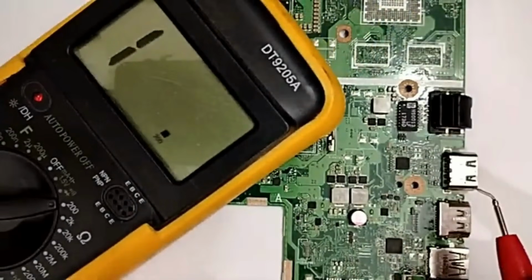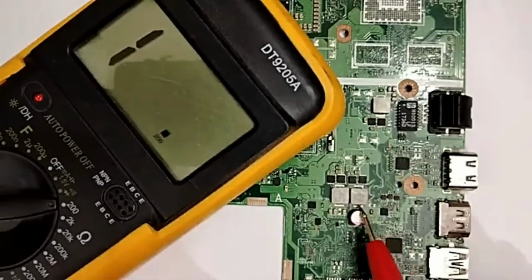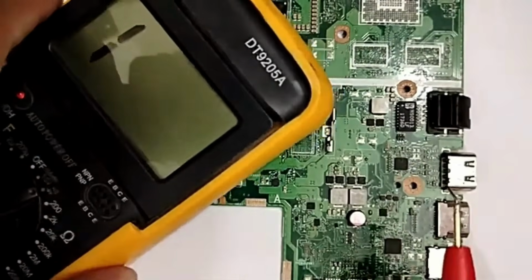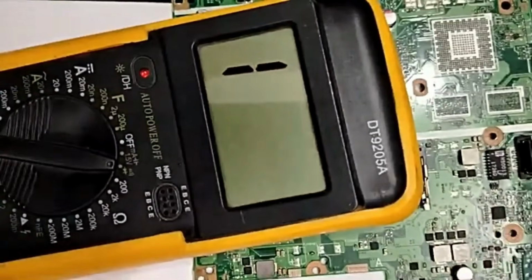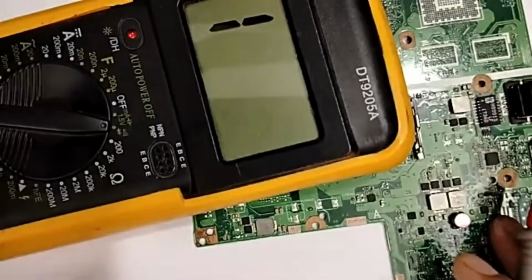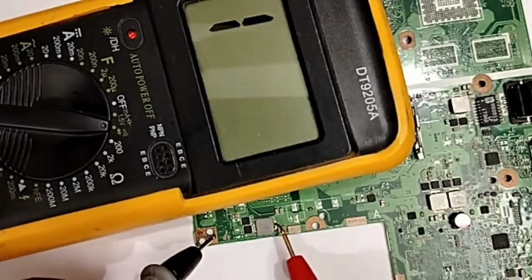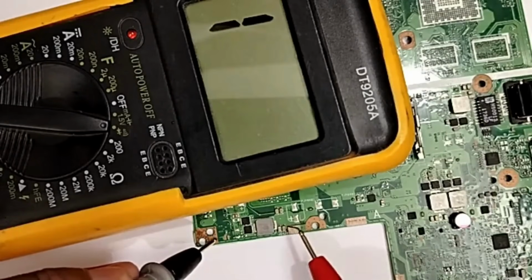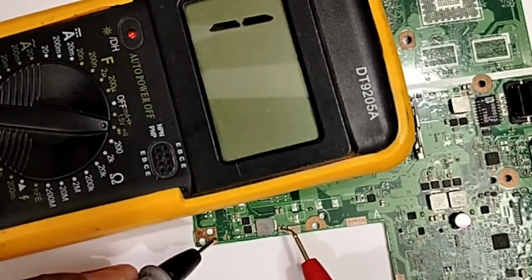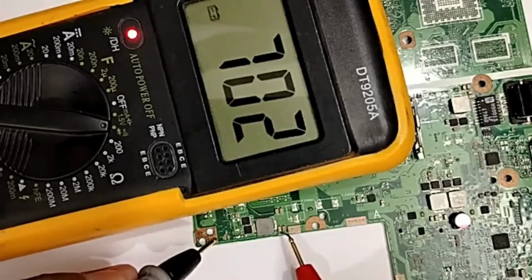Let's check in ohm mode here. Do you see, my friend? High reading, high. That's why we use inductors to locate a short. Let's check this inductor also here. This one here. Okay. Oh, we have 0. Is it 0? No, sorry guys, I touched the ceramic capacitor, because this side of the ceramic capacitor is ground. You see? This side is connected to the ground.